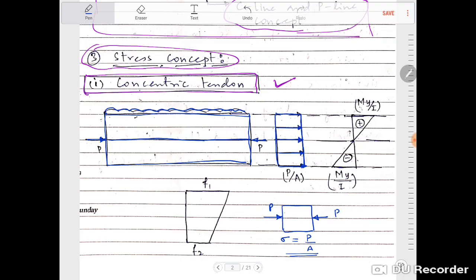The neutral axis becomes useful in the bending case, because in bending you have a part in the beam where the stresses are equal to 0. That does not happen in normal stress. Normal stress is uniform throughout the depth, while bending stress is not uniform; it is going to vary linearly like this. Under this UDL, the top portion will be in compression while the bottom portion will be in tension.